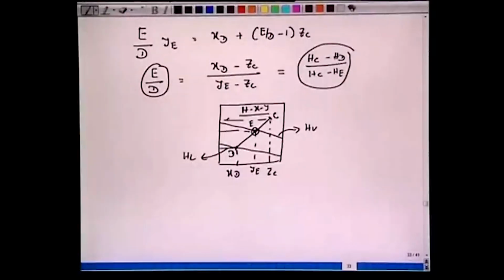So far, what calculation we have done, we have created the HXY diagram. That's one. Once we have the HXY diagram, then we apply this mixing rule. Anywhere on this HXY diagram, if we choose two fluids, whether they are both saturated vapor, both saturated liquid, or one vapor and one saturated liquid, it doesn't make a difference. We are going to apply the mixing rule. Take these two components and mix them. The resulting mixture's coordinates, its enthalpy, has to lie on the straight line joining the two components. This we get from the mixing rule.